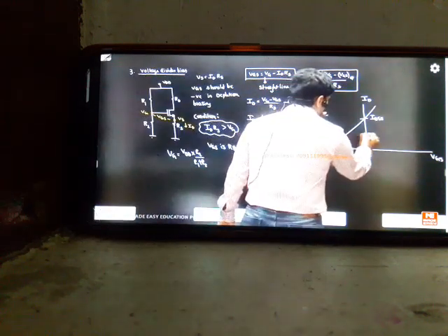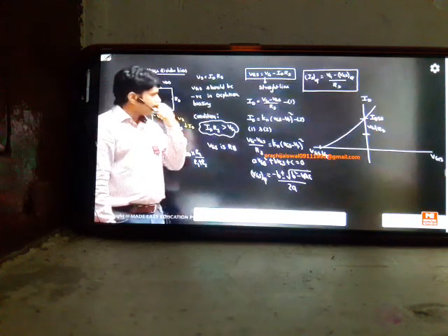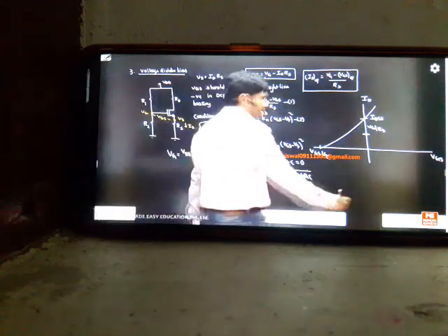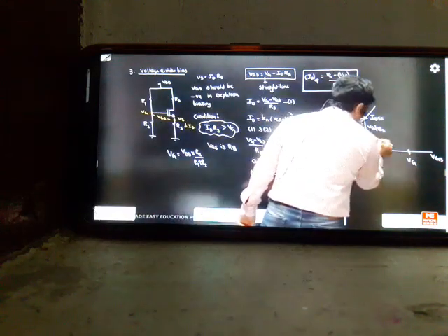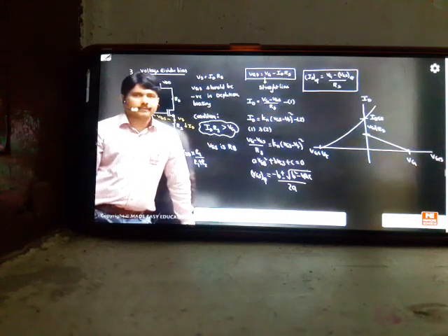Therefore, you may get some line intersection here, VG by RS. This is called ID max we got. If you want VGS maximum, the y-axis should be 0. Then automatically VGS will become the VG voltage. Your VG is a positive voltage here. If you see, this is the straight line, the load line we got from that equation. X maximum value, Y maximum value I found.